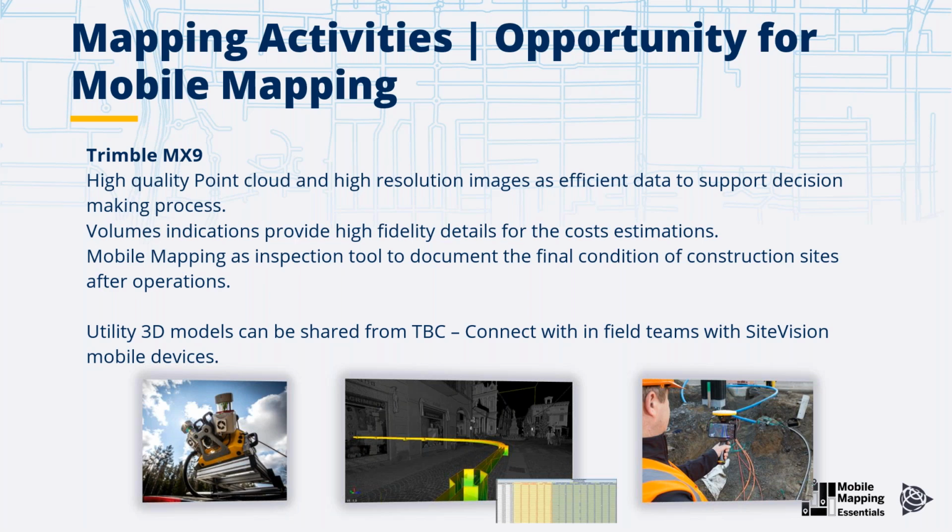Because with the point cloud data, they would like to understand how much material has to be removed from the site, how many trucks will be needed to move this material somewhere else, how deep the trench will be, and how much material will be needed to fill in the trench as soon as the cable has been installed on the ground.